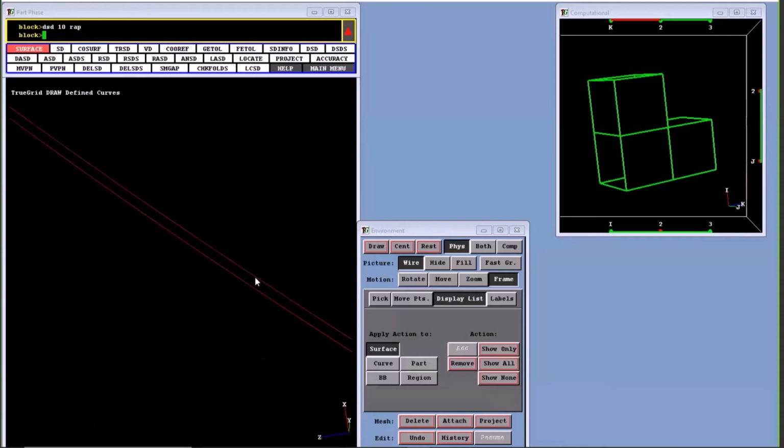Let's suppose this is surface number 7, and this is surface number 5, and there's a gap between them. It's a small gap. They always are small. They're not huge. If it's huge, you've got a real problem. But typically, it's a small gap. You take the union of these two surfaces and say, now project to the union of those surfaces. What does the algorithm do? It projects to this surface and to this surface and moves that vertex or node to the point that is closest. It doesn't try to fix that gap at all.